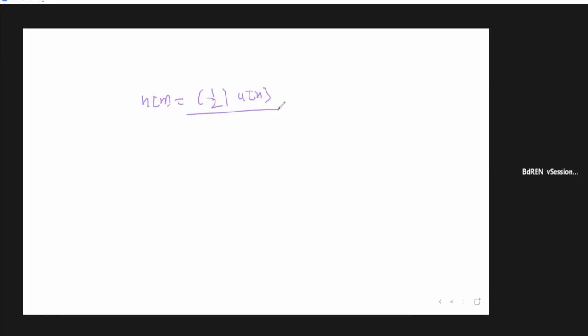Okay, in solving your multiple choice questions, some are saying that some calculations and recalculation must be needed, okay? But what I am repeatedly advising you is that whenever you encounter some representative signal, you have to memorize how the Fourier transform will look like. For example, if we have a signal, we know that this is the impulse response in the discrete time system. You have to find the Fourier transform, H(e^{jω}), in order to understand the filter behavior.